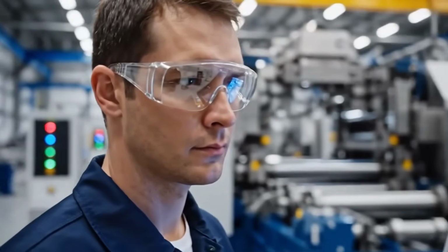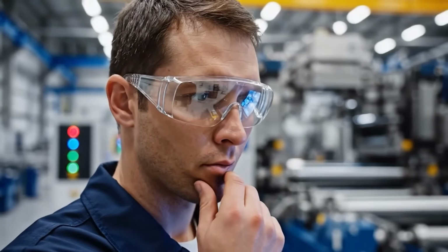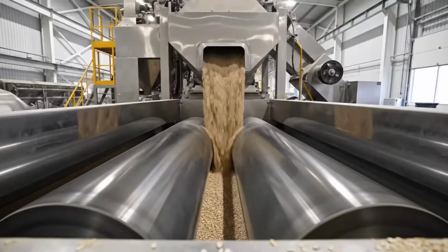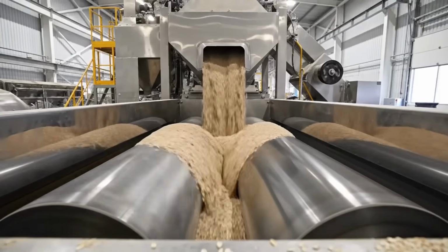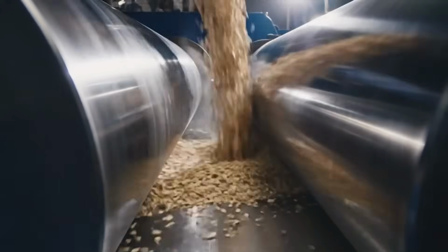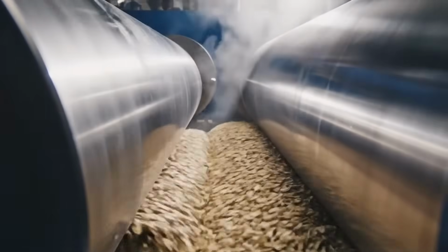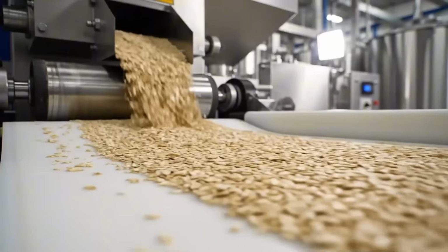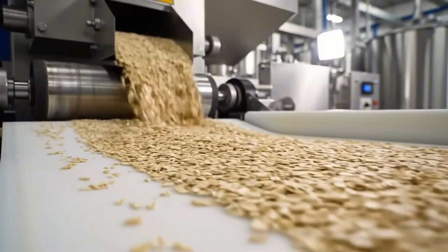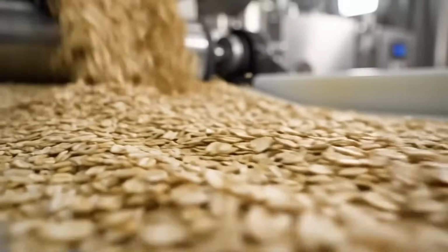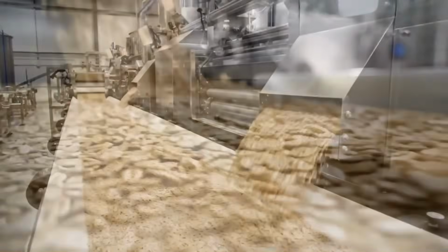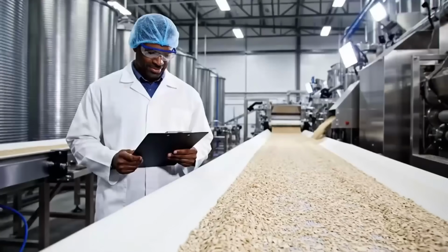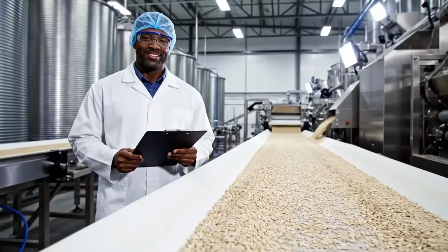Sweetener and binder streams are prepared in parallel. Glucose syrup or similar syrups are held in jacketed tanks to maintain a stable viscosity for pumping. Sugar can be added as granulated crystals or dissolved into a syrup depending on the texture target. Fat sources such as vegetable oil or butter are melted and held at controlled temperature. If nut butters are used, they are warmed to a flowable state and mixed to eliminate oil separation. Emulsifiers can be staged to stabilize the binder and improve coating of dry particles.